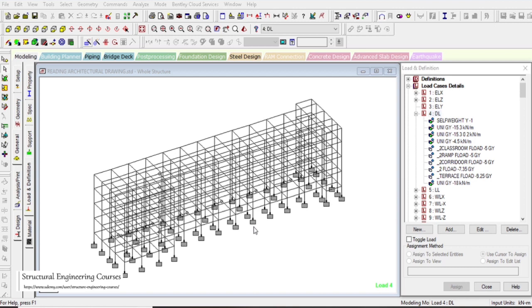All these recommendations are present in the geotechnical report of a project. Before we start the designing, the soil consultant must have done some tests on the actual soil, and he shall always provide you with the geotechnical report, which shall have a recommendation on what kind of footing shall be adopted in this structure.